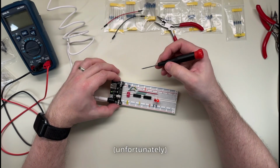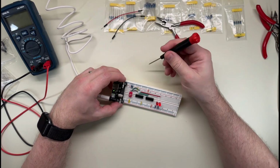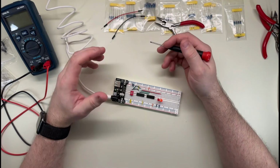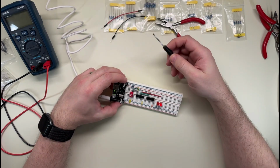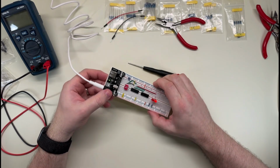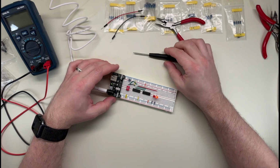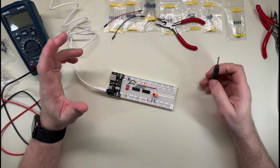I've read a bit online about what values people use for pull-up and pull-down resistors in digital logic circuits, and it seems pretty common to use something like 1K for pull down and 10K for pull up. I don't entirely know why those values are chosen specifically, but they seem common in a lot of people's example circuits. The crazy thing is how many example circuits are out there that do completely different things. They have completely different values. That's true for these LED current resistors as well. Some of them use 330 and some use 220 and some use whatever they've got, I guess.